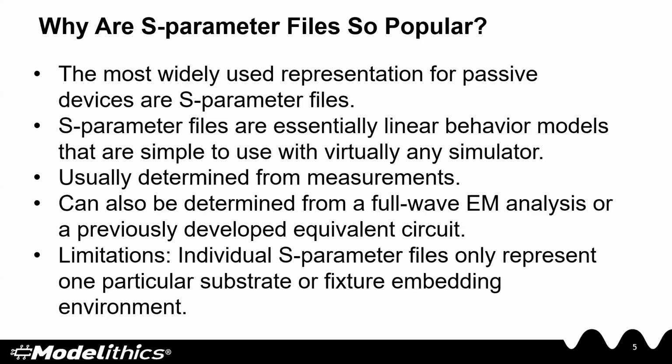However, these models do have a limitation, and that is an S-parameter data file only represents data when using one particular substrate or test fixture environment. However, as a designer, you might be using a different substrate or a different test fixture, so the results that you'll see may not necessarily agree with what's in that S-parameter data file.